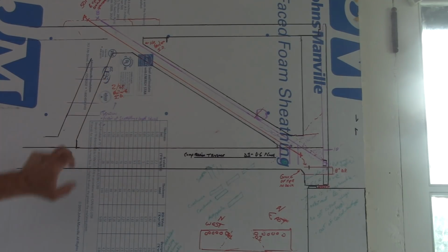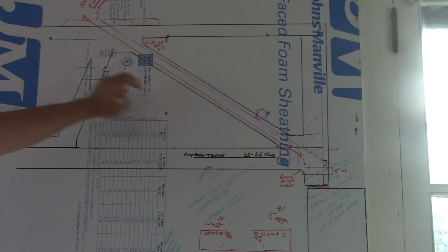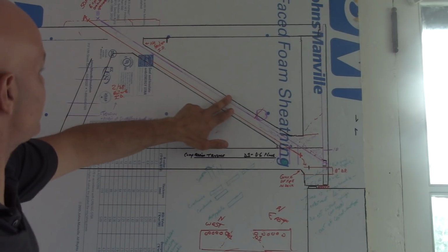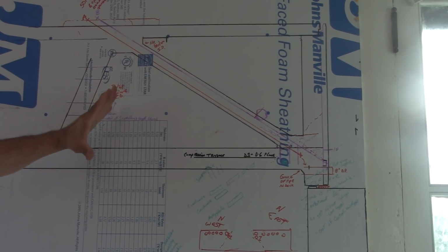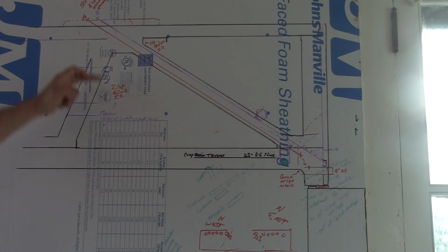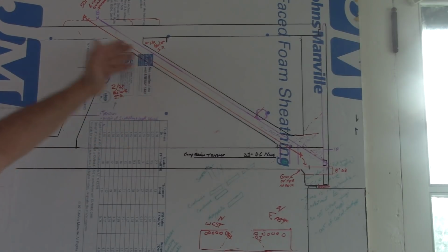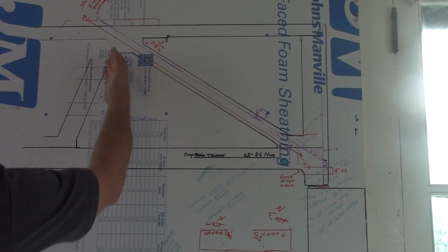And with that said, let's go to the friction of the joints again. So you're pulling this one down, tensioning this one. All of a sudden you see cracks here. That signifies that putting post-tensioning on this one actually created a dropping or a movement between this one and this guy, separating like this. These are parallel with the deck. If the crack was in this direction, I would say this created a cross force that put tension in the member, and the cracks would look like a reinforcement pushing against the concrete, creating tension, following the tension line.